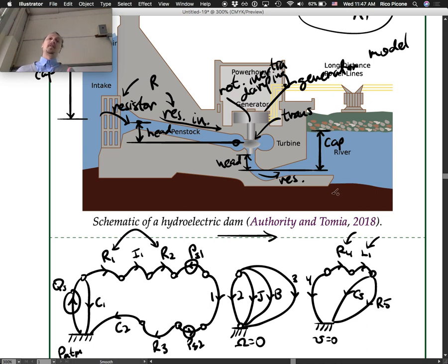So yeah, but you're right. If the head went the other way, if the turbine was at the low point and you went back up to discharge, then the head would be pressing against the other way. And we want water to flow down and through all this stuff, which is part of why the head is dropping here. So the pressure is pushing it this direction. Of course, with this, you're going into the river, so this is pushing back, right? That capacitance of the river is pushing back.